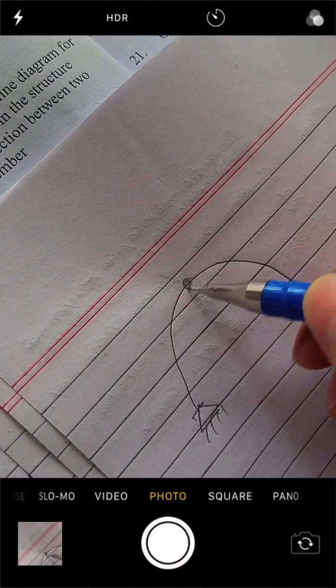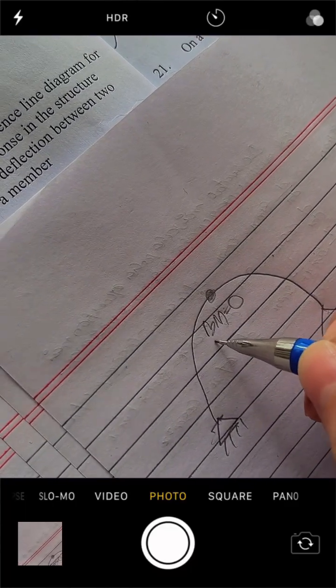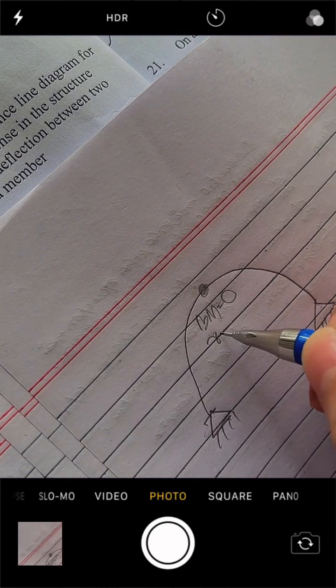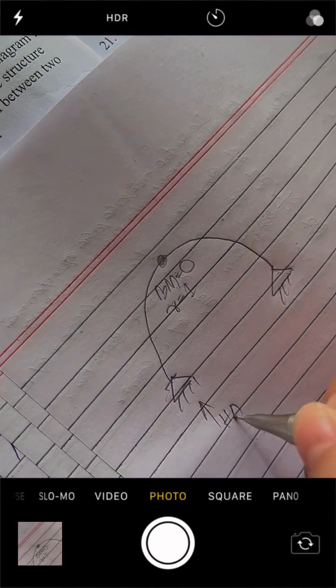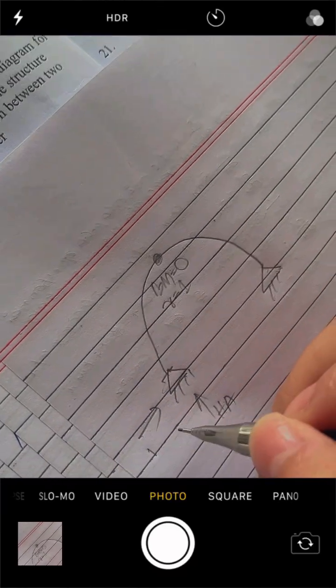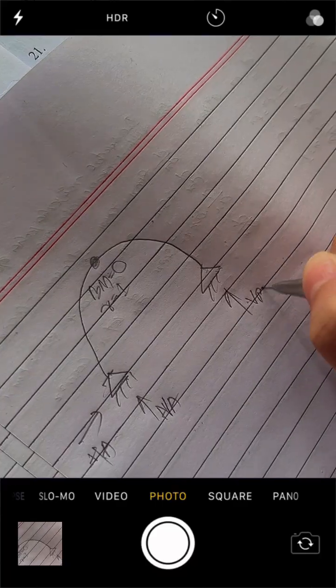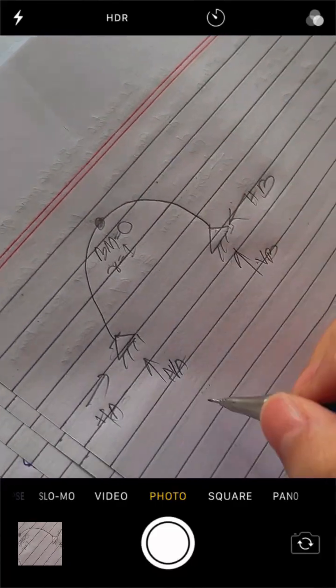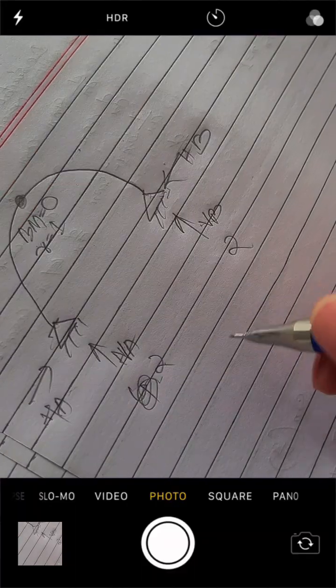This is my internal hinge. Here the bending moment is equal to 0, because of which one reaction will generate. So here it's my HA. For the hinge support, we know that there are VA and HA, VB and HB. So here we have two reactions, and here we have one.